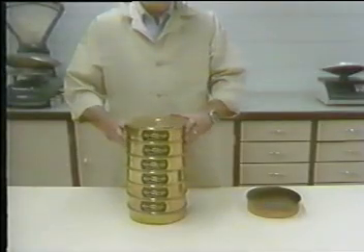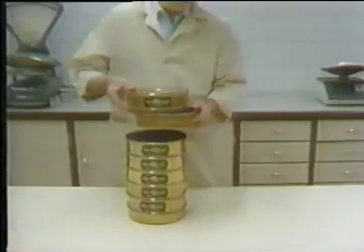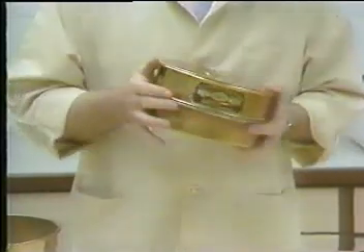Remove each sieve in order, starting at the top, and place a pan beneath and cover on top. Be careful not to lose any of the particles retained on the sieve. Hold the individual sieve with pan and cover in a slightly inclined position in one hand. Strike the side of the sieve sharply and with an upward motion against the heel of the other hand at the rate of about 150 times per minute. Turn the sieve about 1/6 of a revolution every 25 strokes.